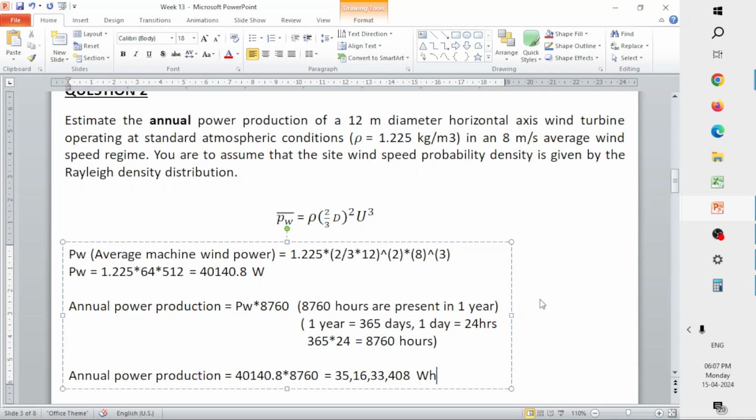One is because the wake that is formed is actually rotating, another is the drag, and another is due to the tip losses, and apart from that you have other kinds of losses contributed by the different components present in the wind turbine, right? So when all these losses get combined, you can actually harness only approximately 30 to 35% of the power that is available.